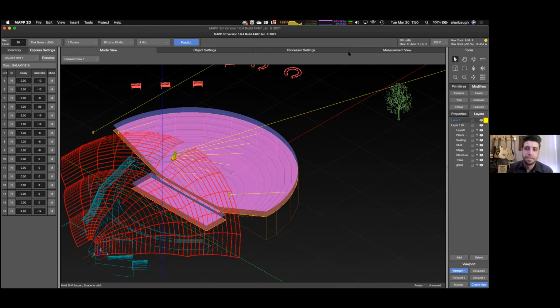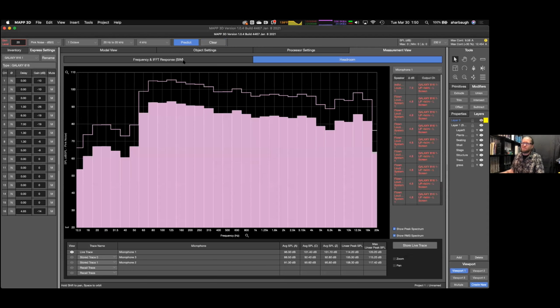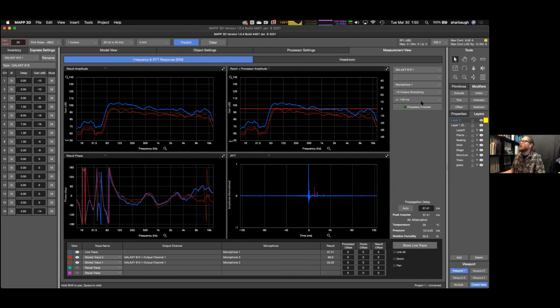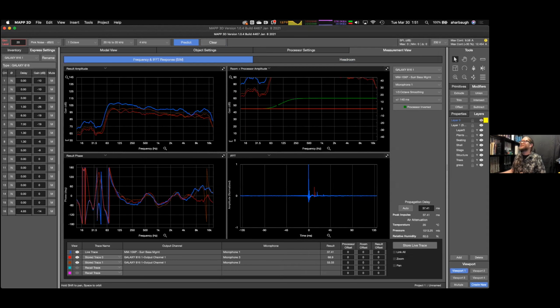So yeah, if we just look at a trace of our microphones in the model, it's not going to be EQ'd to what we wanted to do. But let's pick an output channel such as my left screen channel, or a different one, right there. So for my sub of my surround bass management, I have essentially a high pass filter made out of U-shaping. And this trace right here, the green trace, that's not necessarily what a high pass filter is doing, right? Or a low pass filter, I should say. Sorry about that. This is what it's actually doing.